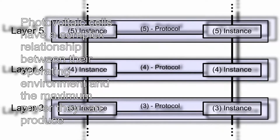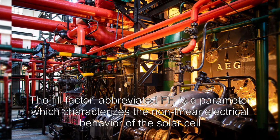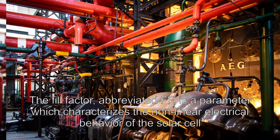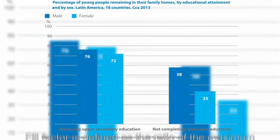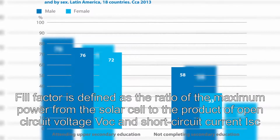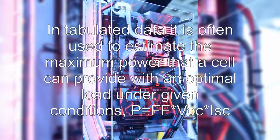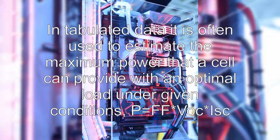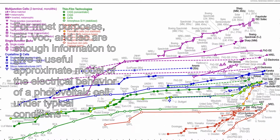MPPT devices are typically integrated into an electric power converter system that provides voltage or current conversion, filtering, and regulation for driving various loads, including power grids, batteries, or motors. Solar inverters convert the DC power to AC power and may incorporate MPPT. Such inverters sample the output power from the solar modules and apply the proper resistance so as to obtain maximum power. The power at the MPP is the product of the MPP voltage and MPP current.